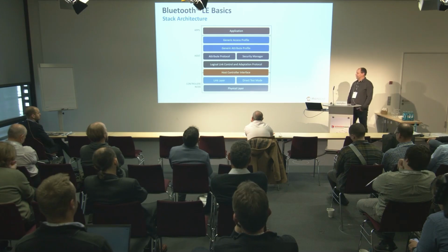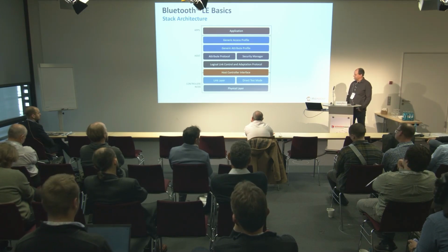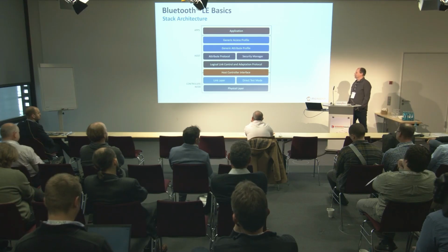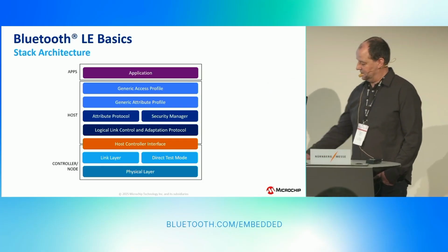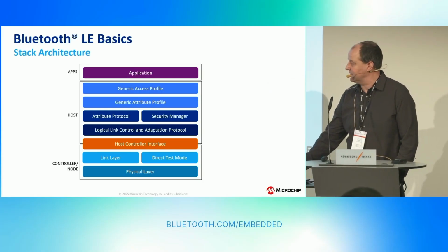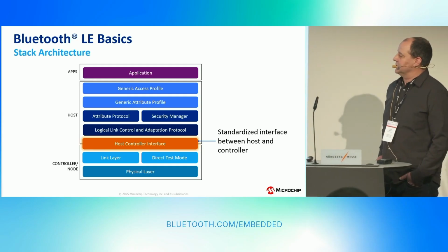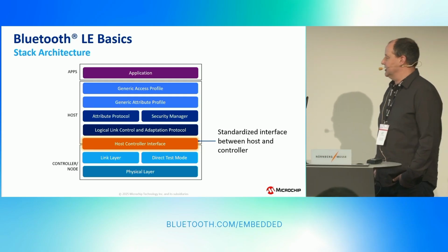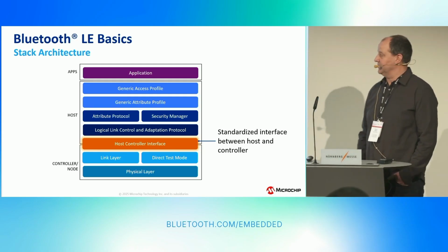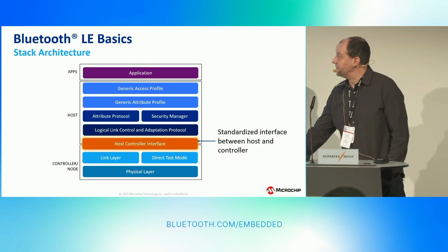This seamless connection switching feature is completely implemented in the controller part. So the host part communicates via the HCI interface with the controller part, and we extended this interface to implement the feature.